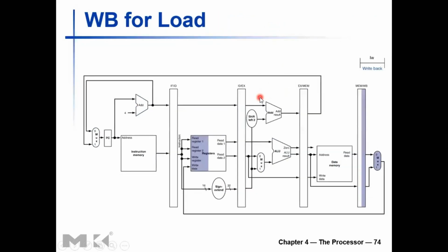So those bits of the address are also provided here through a multiplexer, right? That multiplexer is not shown here since we are not considering R-type, but as it's shown in this particular diagram right now, we are reading the write register address from the pipeline register, which corresponds to the instruction that was fetched in the previous clock cycle.